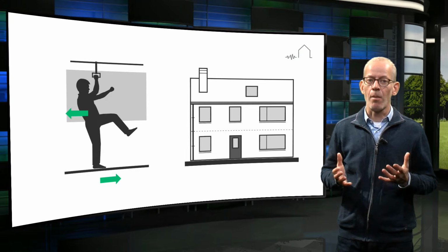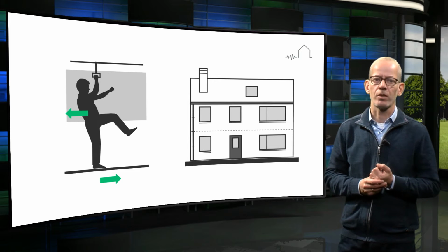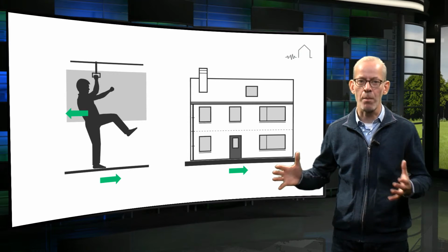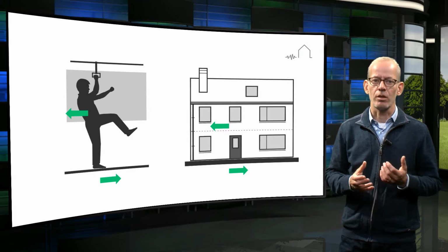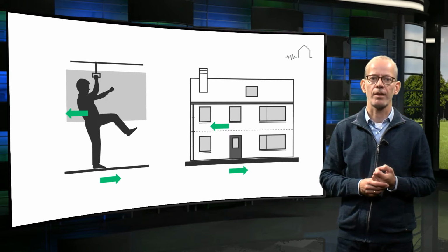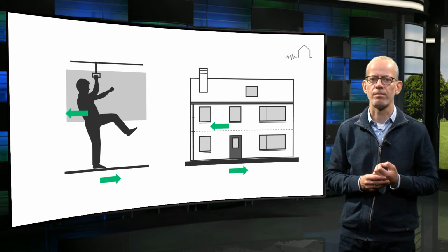During an earthquake, a masonry house actually faces similar difficulties. The underground and the foundation are accelerating while the mass of the house wants to remain in place. This results in various forces in and on the structure. And let's now have a look at what this means for a typical Dutch house.